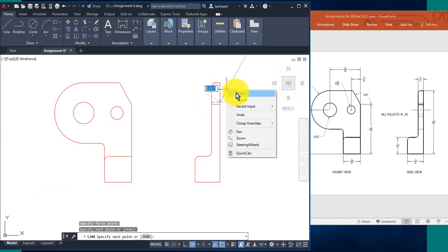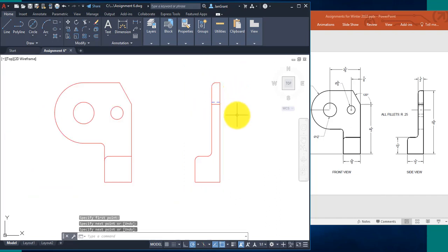Now the first thing you'll see is that the hidden line is a little bit big in scale. It's okay if it is. If you want to, at this point, you've learned about LT scale to change your line type scale. If you wanted that to show like 3 little hidden lines, you wanted to kind of make it a little bit tighter, you can by typing in LT scale. I'm going to leave it like that.